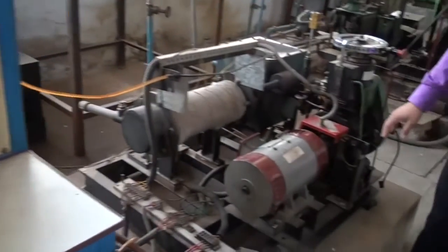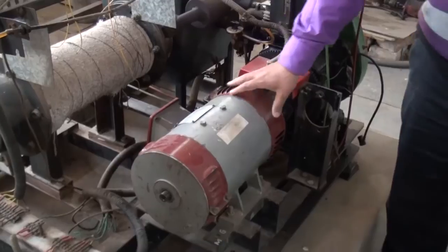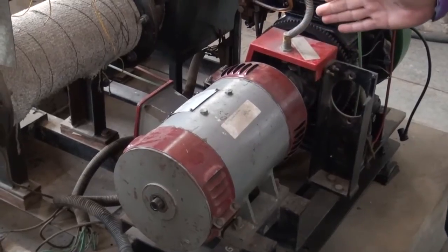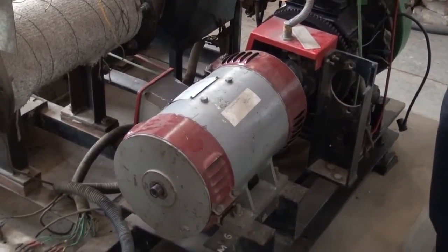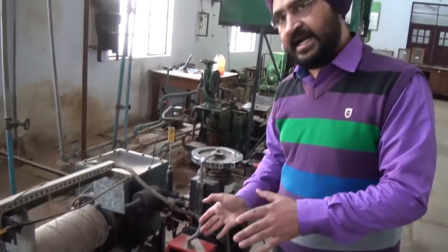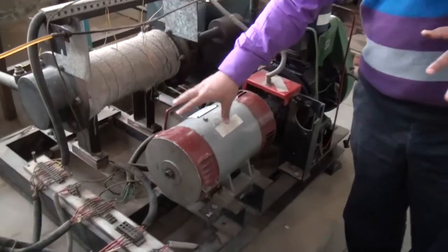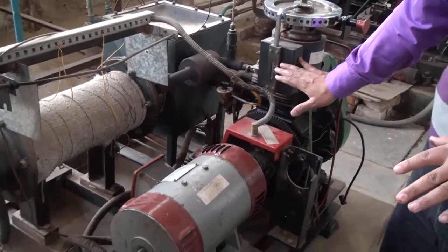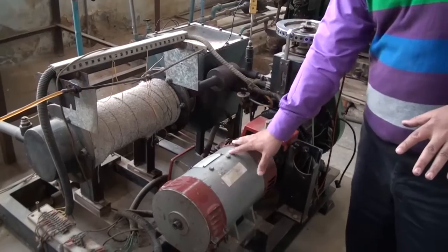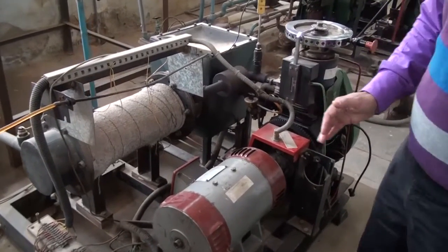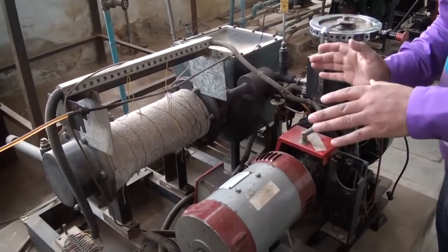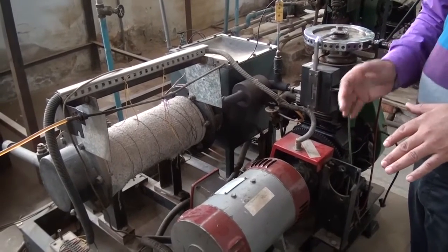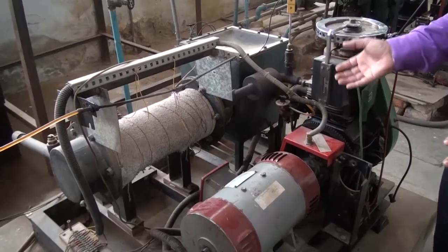Now another thing is the generator, DC generator cum motor. As I told you, we are going to run the engine in two modes. One is the generator mode, where the fuel is consumed and combustion takes place, and the second is motoring mode. In motoring mode, no fuel is consumed, only this motor is going to run this engine. So this is the generator cum motor, it works in reverse mode. So why are we doing this? Because frictional power is the same whether you run it in engine mode, generator mode, or motor mode, because the piston cylinder arrangement is moving. So that is the main thing.